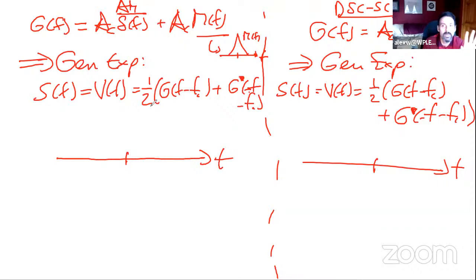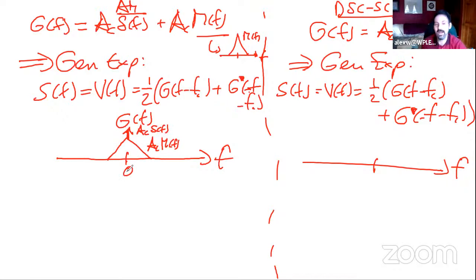So, and again, this is the magnitude response. There's also a phase response, but I'm not going to spend time trying to derive that, all right? Just for sake of fun, we're only going to look at the magnitude response. So G of f for the AM modulation is going to look like this. It's going to be M of f, that shape, multiplied by AC. Oh, and a delta right on top there. AC delta f.